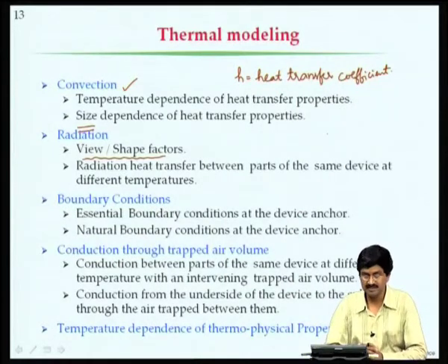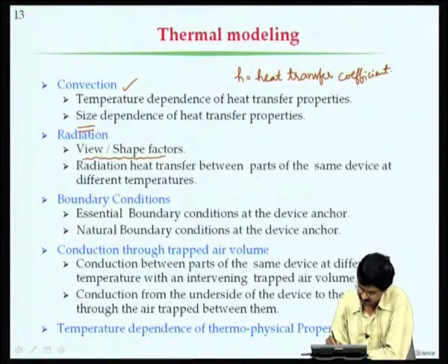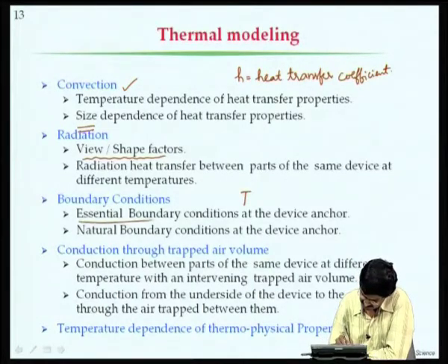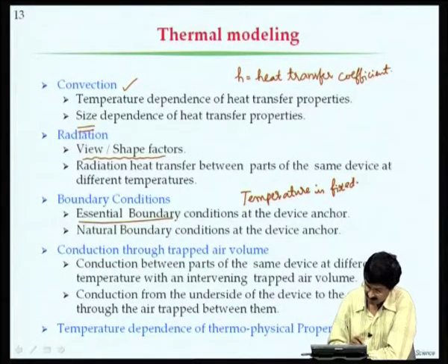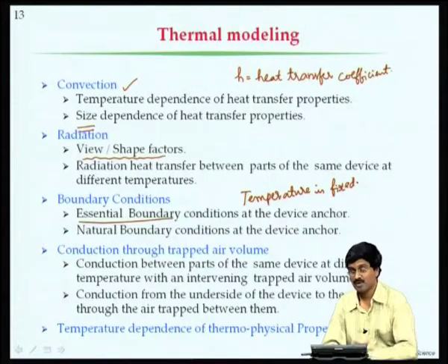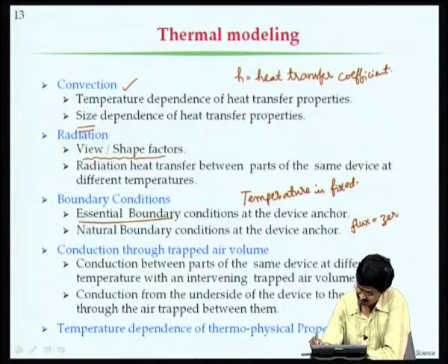And the boundary conditions in this problem can be essential boundary conditions, meaning temperature is fixed. When we say essential or Dirichlet, it is where temperature is fixed. Natural boundary conditions are those where temperature is not fixed, but flux is 0.